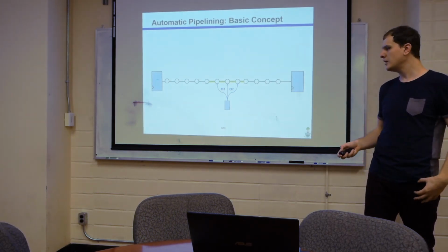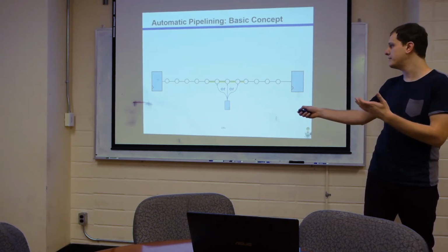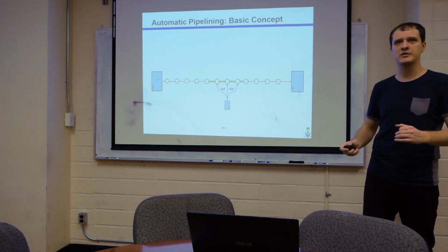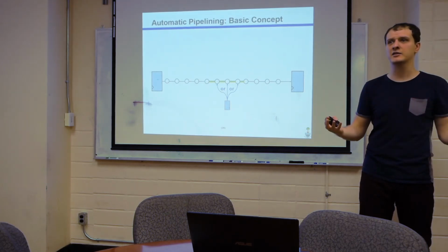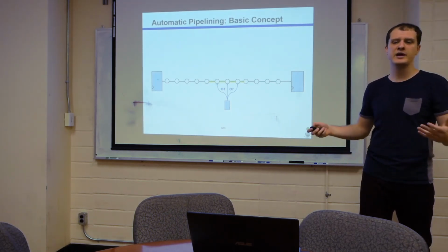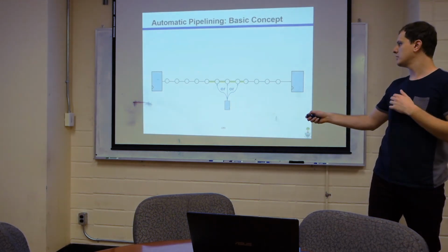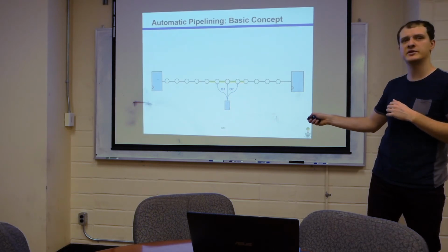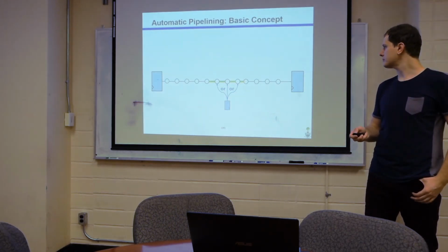good. The basic approach for pipelining, at least this kind of linear link, is I need to find all such minimally overweight segments along this path and create a constraint that says along this segment, add at least 1 register, which in terms of the L variables means number of registers here plus number of registers here plus number of registers here is greater than 0.